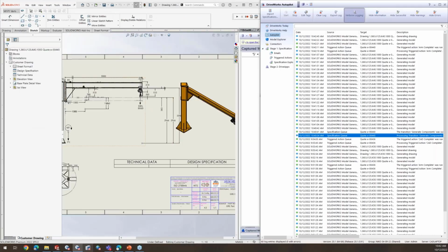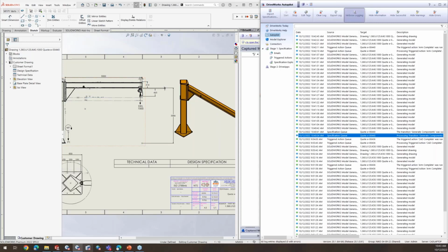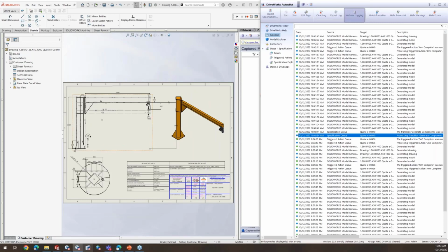We're going to take a few moments to tune up the drawing. We're going to do a variety of things, including auto sizing, automatically setting the scale of every view, the positioning, the size of the view. We're going to delete annotations that are not required. We're going to update data tables, update the title block. Pretty much everything that you would think to do manually, we're just going to do automatically. If you look carefully, you'll see dimensions being positioned just so. By the time this thing is done, I don't want any human hands touching this before it's sent off